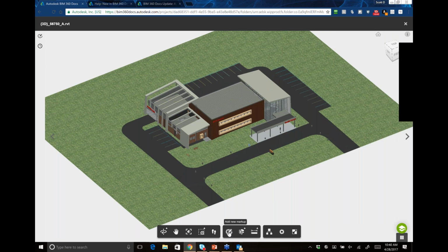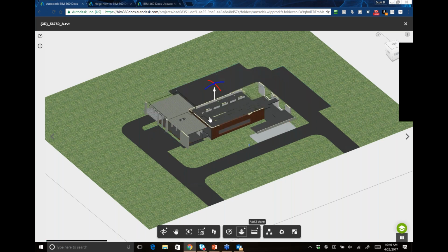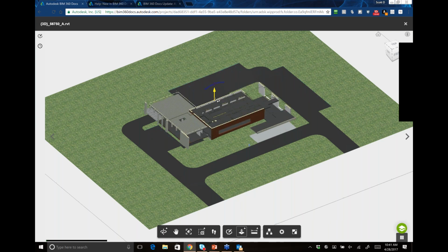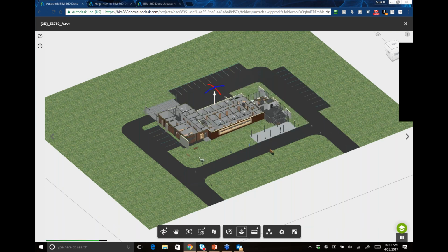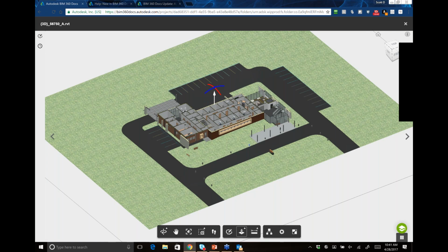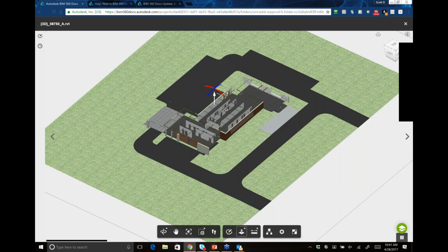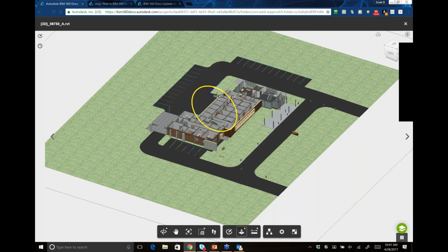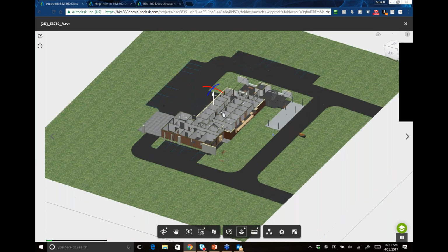We can also do markups in 3D, so that same markup that we did a moment ago. We can also do 3D section analysis. So this is really key for those people that are maybe the non-Revit types on the project that just want to get in and explore a model with a very simple, quick lesson on how to toggle on the planes here, X, Y, or Z, or even a box, and then the section controls, which is really just this gizmo here, allows me very quickly and easily to do a 3D section.